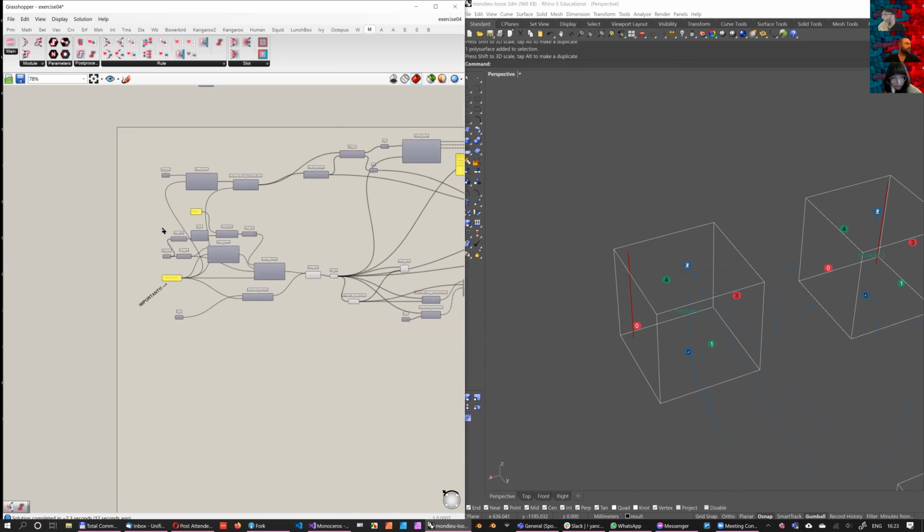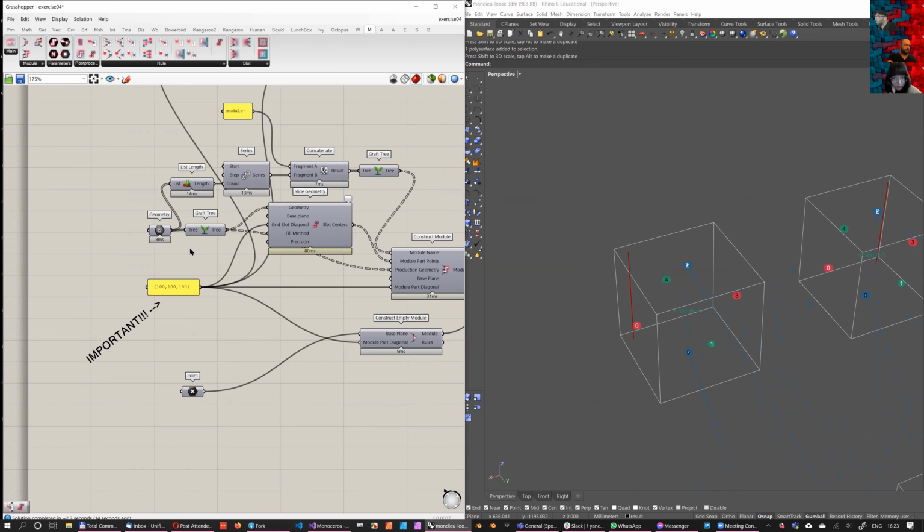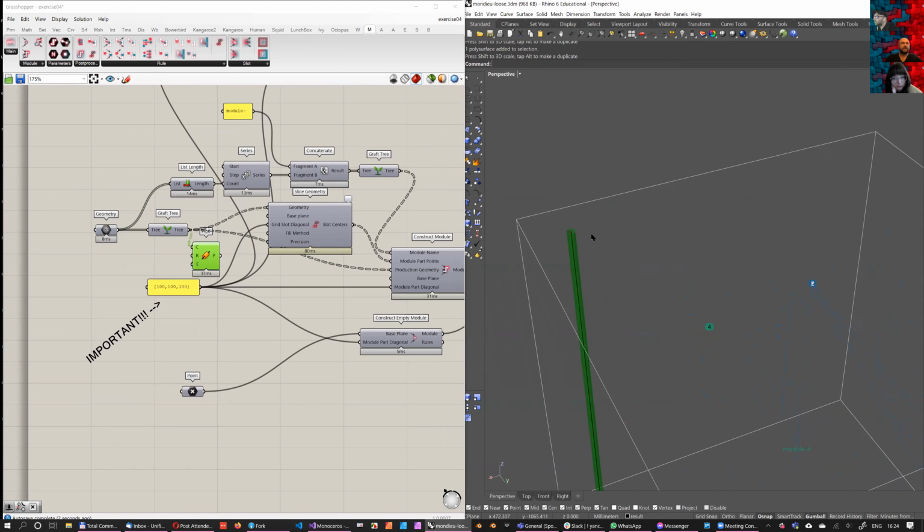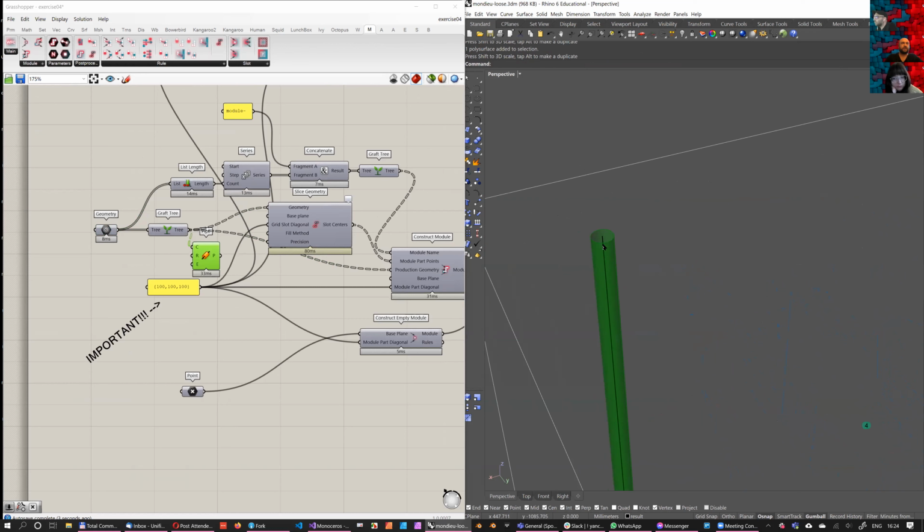I will show you. So if you make a pipe out of these curves here, and the pipe here is open, this is a naked edge, because there is a surface and you can fall over the surface, and there is a naked edge. It means an edge that is not connected to any other subsurface.